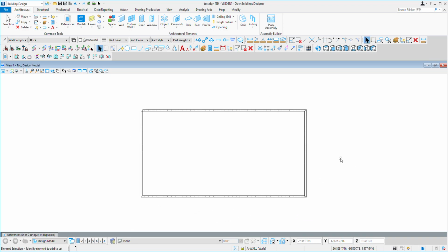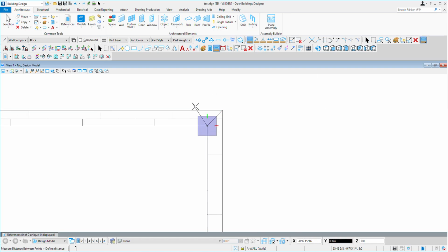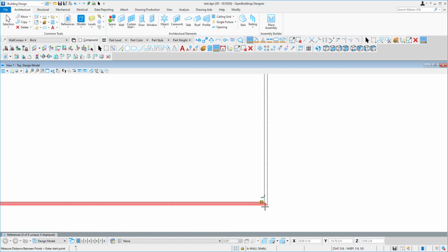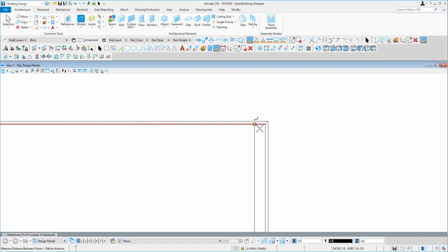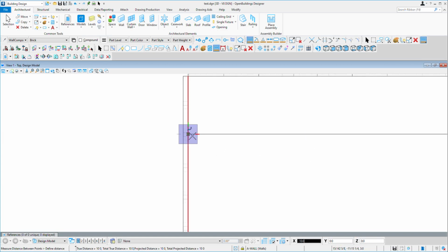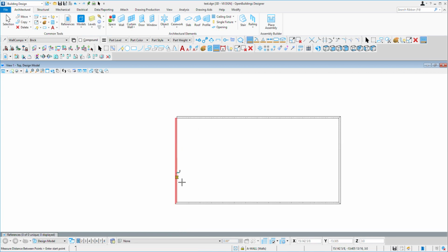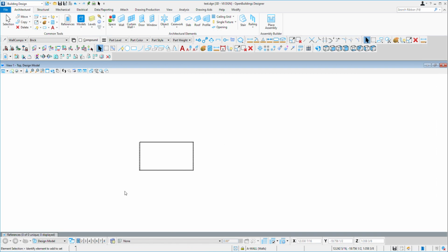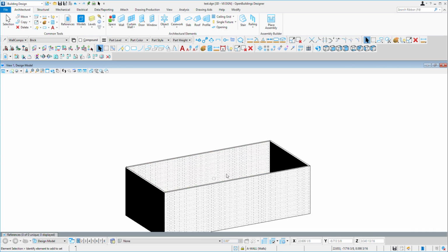If you want to check which dimension you have followed, just check like this. Click, pick this one and enter. Here you can see it is 0.1, and the length will be 5.2 meters because of the 0.1 and 0.1. So the internal dimension will be 5 meters, and the internal length is also 10 meters, with a 0.1 meter wall here. So this is for the wall only.